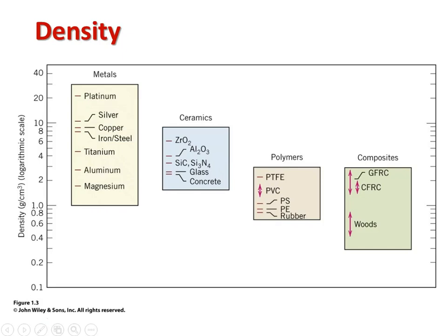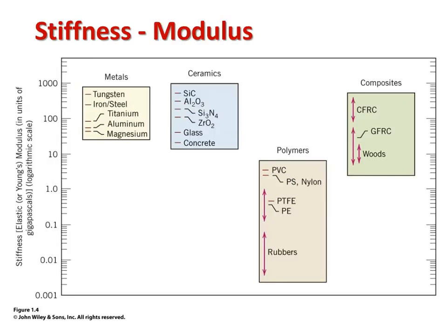So in terms of density, metals, you better be getting something else for them in terms of properties to effectively pay for the high density, which will cost you, even if you don't have a lightweighting application, in shipping and shipping disposal associated costs. Okay, stiffness or modulus. This is an indication of how much a material deforms under a given stress or load.